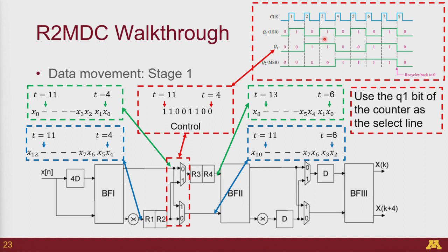Yeah, I wasn't asking that. There are two multipliers here, right? Are both multipliers reading from the same lookup table, or are there two separate lookup tables for these two multipliers? The easier implementation would be two separate lookup tables, because if you think of how it would be implemented in hardware, this would essentially be implemented as a ROM.